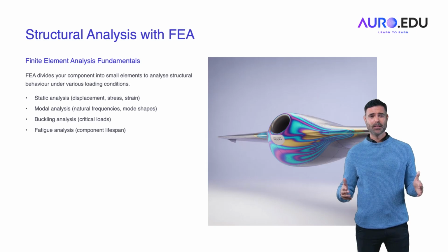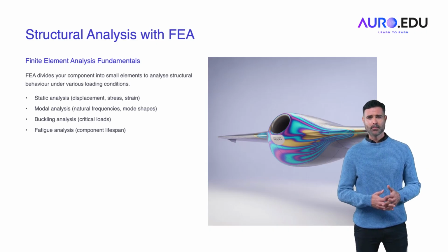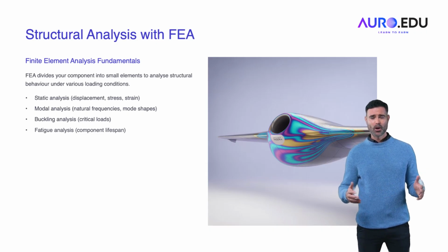Structural analysis with FEA divides your model into small elements to simulate stress, strain, buckling, and more. You'll apply real loads and constraints to see how your component behaves under pressure. Modal analysis lets you understand vibrations, critical in aircraft. Fatigue and buckling give you a sense of long-term reliability. Tools like ANSYS, Abaqus, or Nastran will be your playground here.